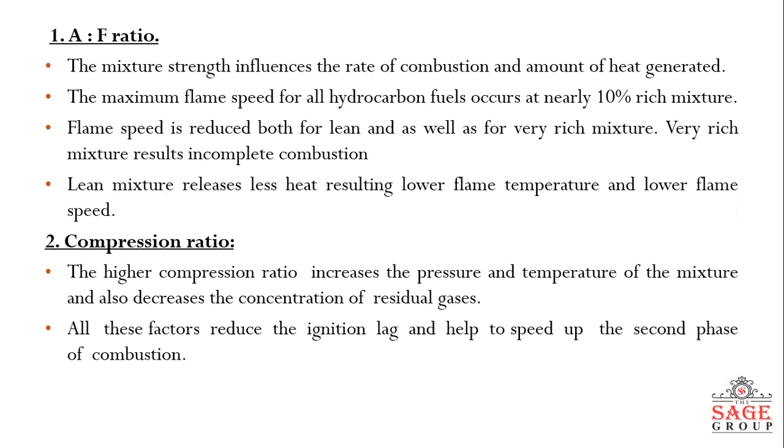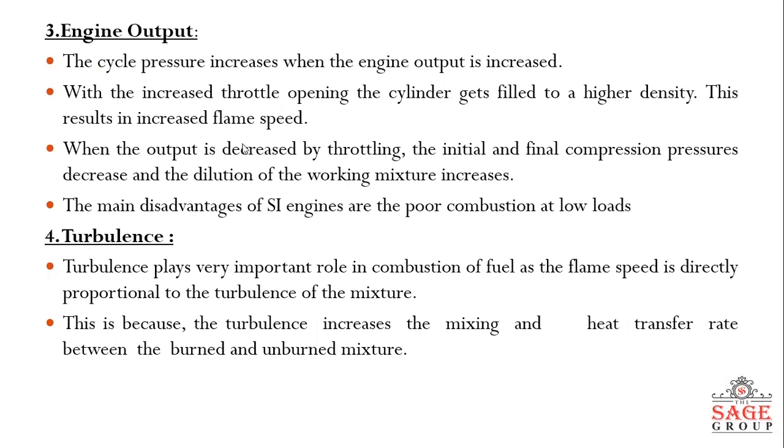This increases the peak pressure and temperature, and the total combustion duration is reduced. Thus, engines having higher compression ratio have higher flame speed or lesser combustion time. Then, engine output. The cycle pressure generally increases when the engine output is increased.